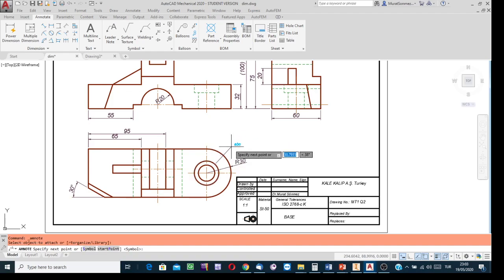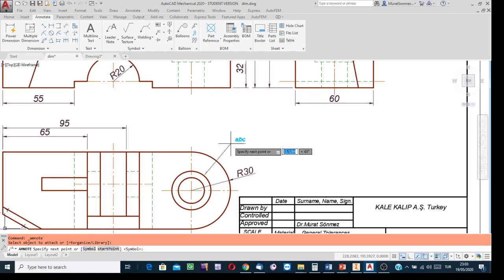move the cursor away, minimum 10 millimeters away, till you reach such a point. You know, the leader line should have an inclined portion and a horizontal tail. So don't move the cursor vertically, don't move the cursor horizontally. Move it in the inclined direction. And then after reaching an empty place to show the annotation using an inclined leader line, make a click and then right click.